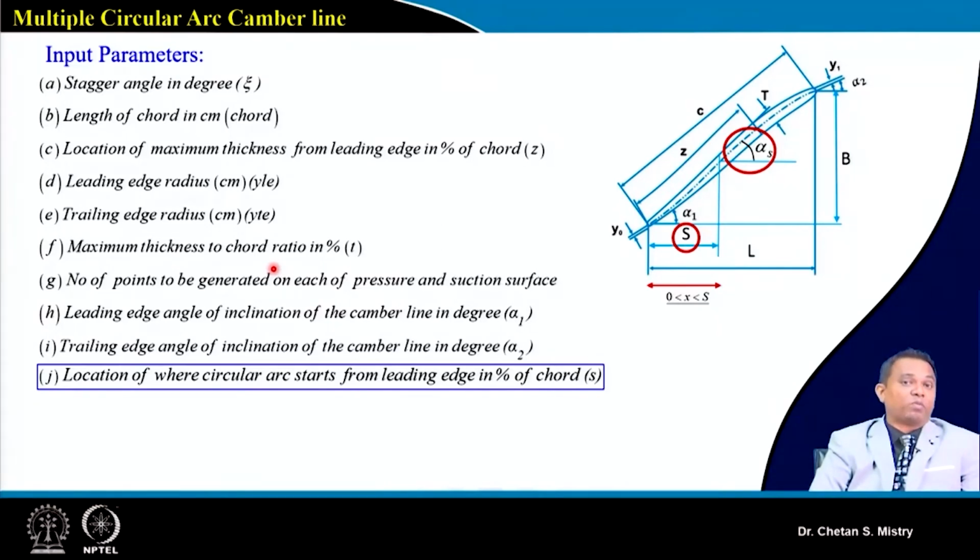This is one of the methods we have discussed. We will have a straight line followed by a curvature, or a circular camber line. So, as per how we want to manage our flow on the suction surface of our blade, we need to modify or make our camber line.